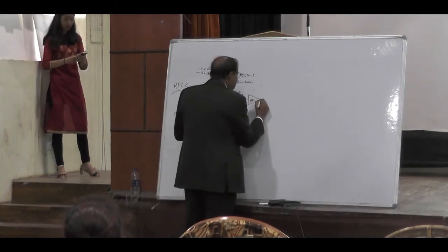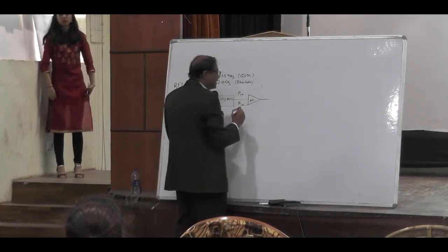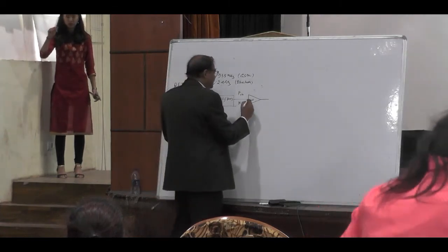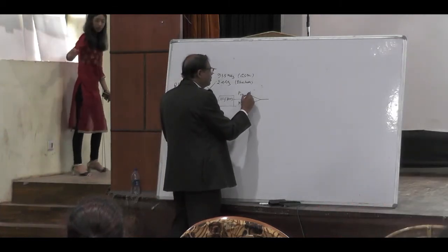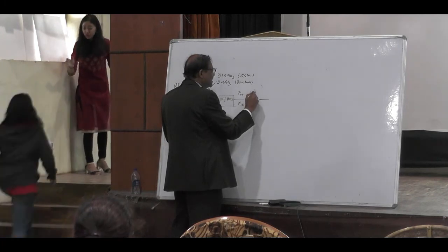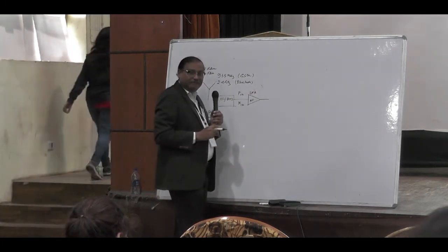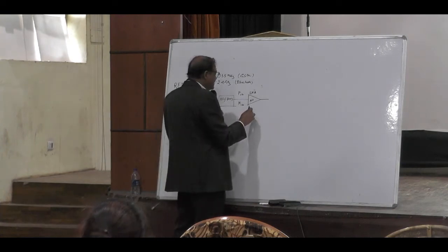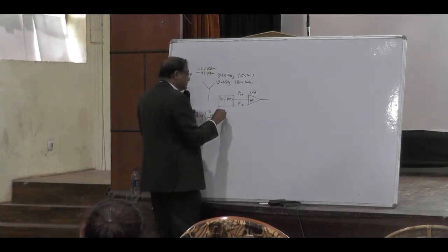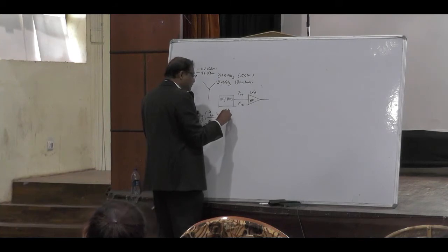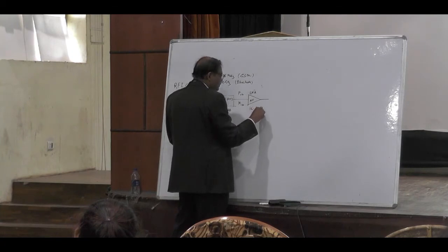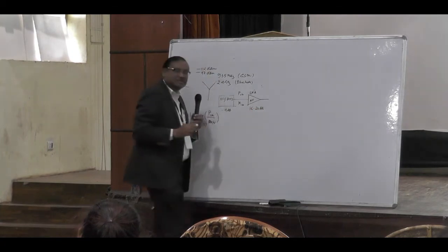And finally, after this, it will come with a gain, say around 16 to 20 dB. This particular block is the low noise amplifier. This is the amplifier with emphasis on low noise. Its gain is normally, for example, if the loss is say minus 4 dB, then the gain normally of a low noise amplifier is 16 to 20. This is the typical gain.